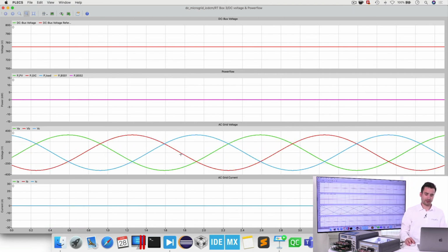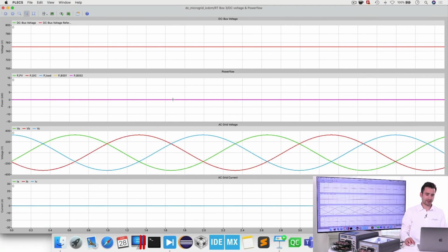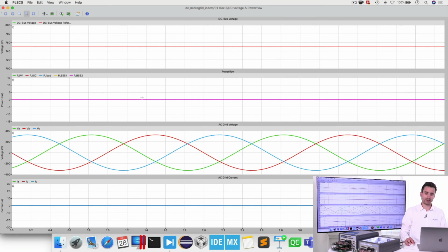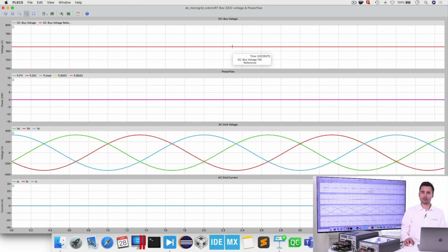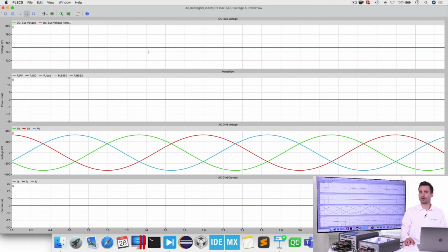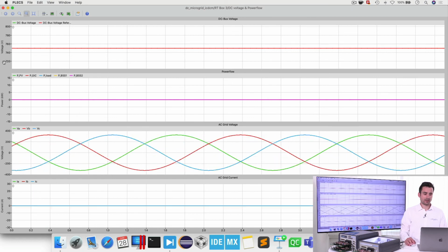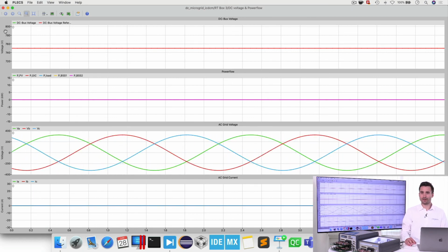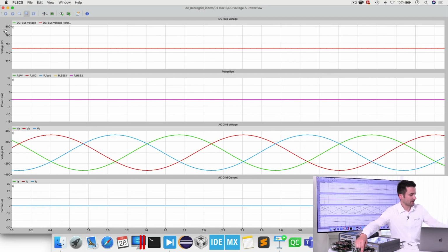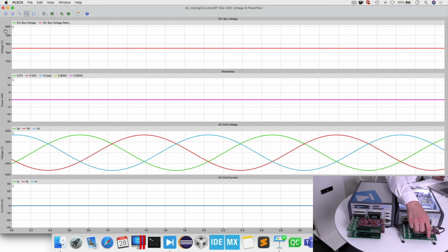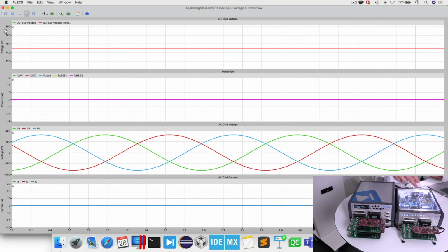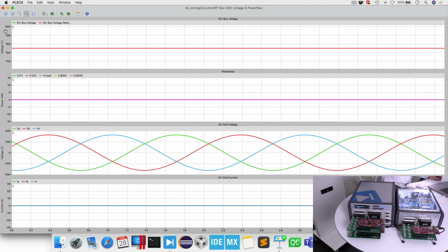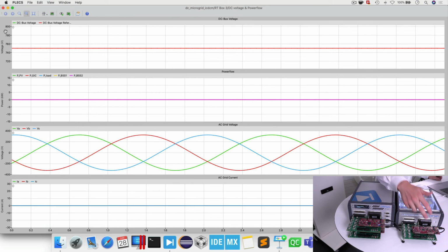So we can see here the grid voltage. We see that there is no power flow at the moment happening in our microgrid, and that the DC link voltage is at 0. So our DC bus is fully de-energized. Actually, I configured here those dip switches that you see here on this view in order to give an enable for this battery storage system controller. So if I toggle here the 2 switches, the DC link startup phase will be initiated. So let's do that.